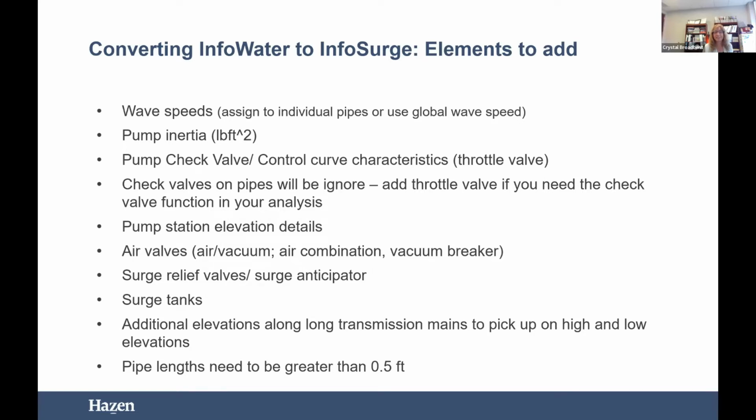Pump inertia, I advise you strongly to get that from the manufacturer. However, there is also a tool that will help you figure out pump inertia if you just can't get that information from the manufacturer. We do suggest adding your check valves or your control valves.